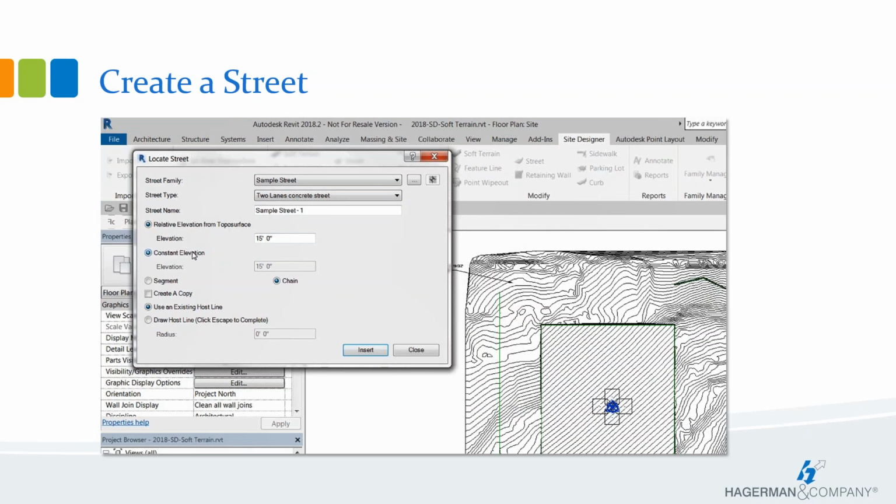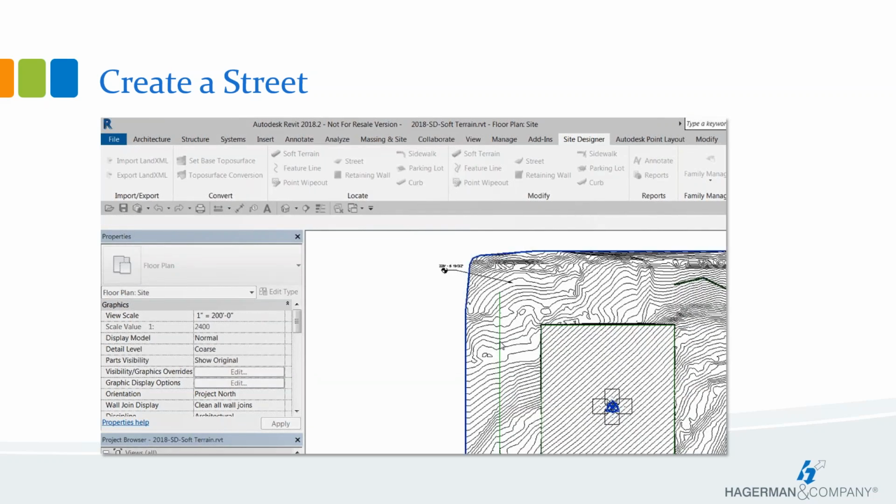This will give us a good amount of site rework, which is exactly what I want. I am choosing 260 for the elevation, so it should get a good amount of cut and a good amount of fill. Everything else is about the same here, except I should have selected create a copy. Otherwise, my model lines get absorbed into the sketch.